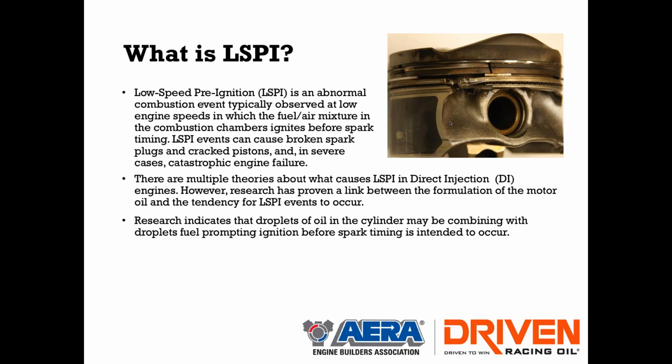We've even done testing where we took fuel and ran it through the octane tester and then began adding oil, different oils with no additives in them, just base oil, to the fuel to start checking the octane level, to see what would begin to happen at different levels and treat rates and with different types of additives, and the effect on what happens with the octane. We were able to really see that there's a link here, and we need to investigate what's causing this LSPI and what in the oil is contributing to it happening.